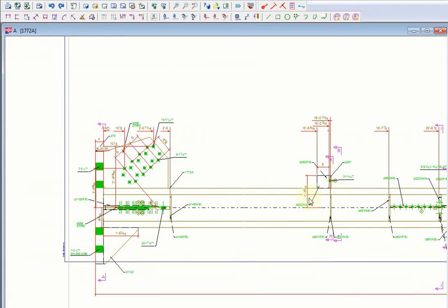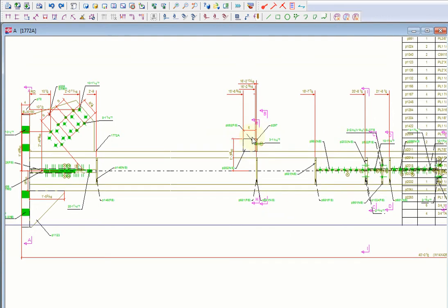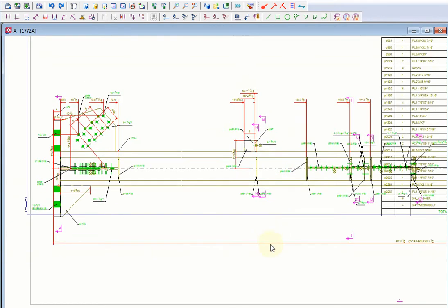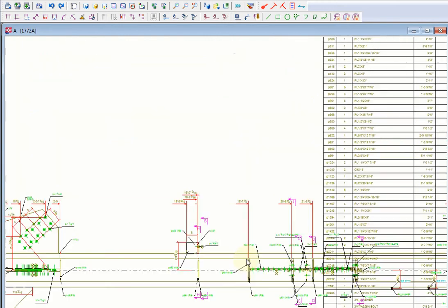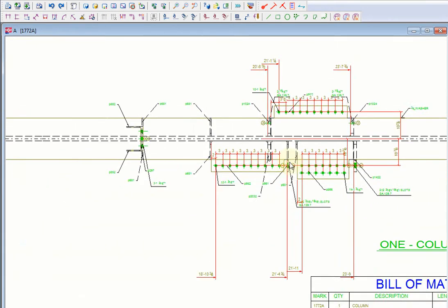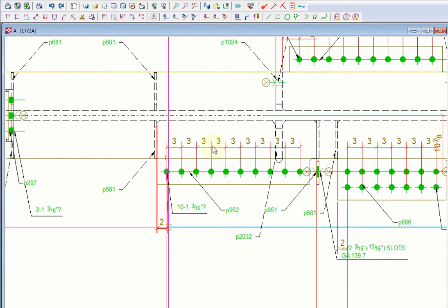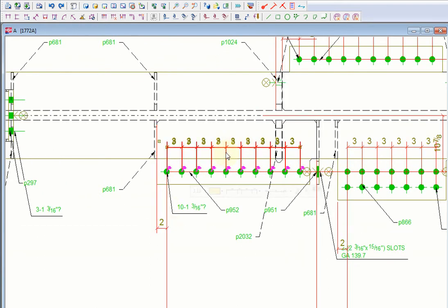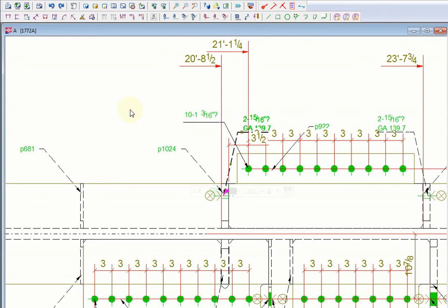If you set the secondary bolt display properly, they will show on the main view or section view. You can see this is a busy drawing, but every single piece should be properly located. And you can see this is controlled by the secondary bolt, and this is controlled by the column shear plate.